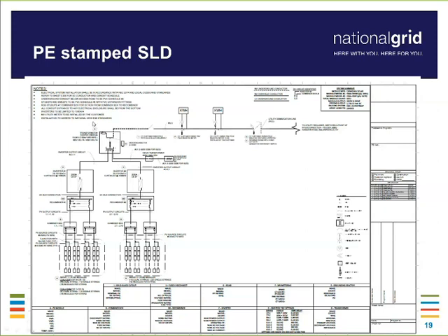Along with the transformer, we would expect to see the sizing of the unit, the voltage ratings, the turns ratio or the step-down voltage value, and the impedance value if needed. All this information would be expected to be shown on the transformer. The configuration of the transformer, whether it's delta-Y, YY, Y grounded, whatever that configuration is. In this case, I believe there's a neutral ground shown on there.